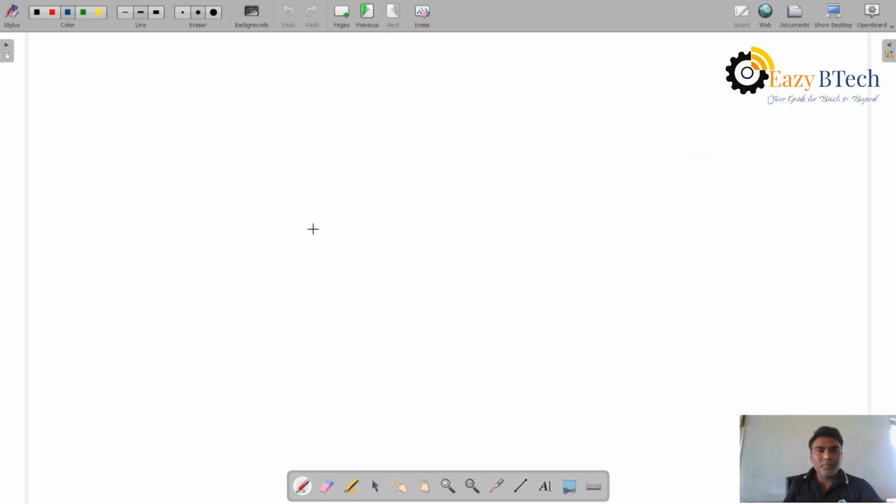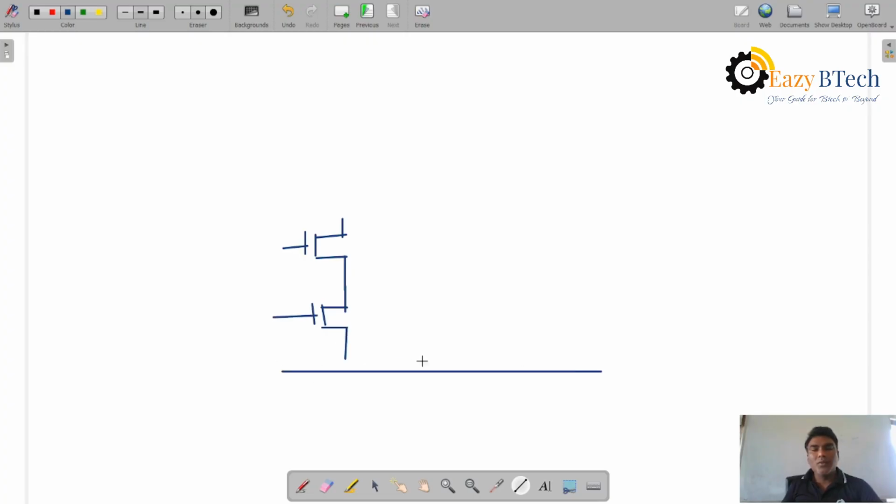Right, so first you can draw A plus B. A and B are in series, because AND logic is here. You see this one, A and C. Any complex gate is given, you can see the logic A in NMOS. So CMOS design means NMOS pull-down, and the complement is PMOS. So A and B are in series.